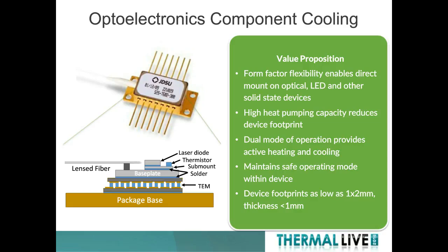Also, finally, as in all thermal systems, the heat sink and the interface resistances have to be carefully considered in the design. So in some ways, this is a very straightforward system in that there's a thermistor, in this case, that you see on the slide, measuring the temperature. The thermoelectric can be used in heating or cooling mode to bring the laser to the same temperature in as wide a range of ambient conditions as possible.